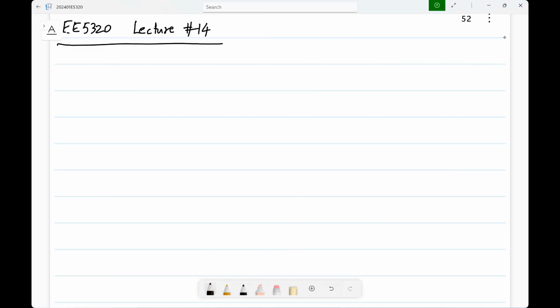We have looked at various factors that affect IC design. Some of it is due to the nature of IC fabrication. We have process variations, and we anyway will have temperature variations. So those things you have to deal with. Either you have to make your circuit such that it's insensitive to these, or you have to have ways of compensating for them and so on. And in addition to those, you will have random mismatch, which will cause some effects, mainly DC offset in amplifiers and so on. So you should know how to analyze them.